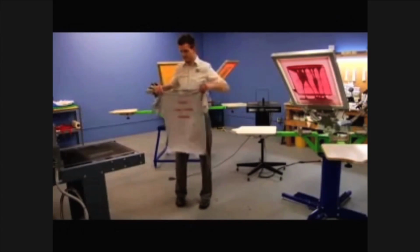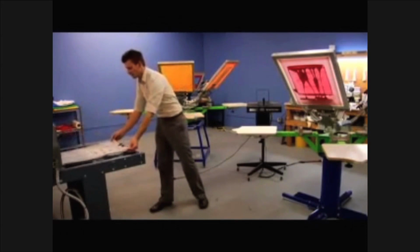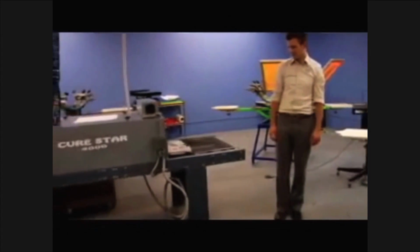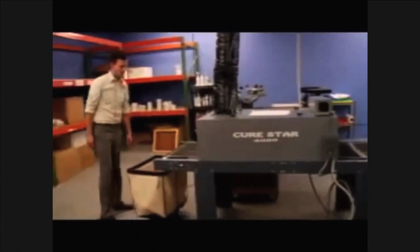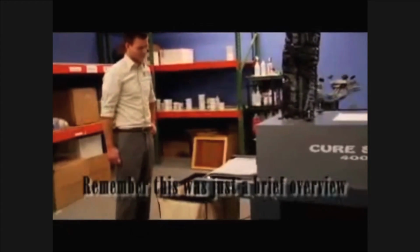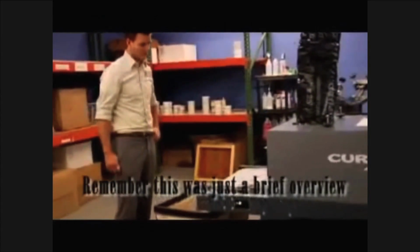When you're finished printing onto your shirt, you need to do a final cure of the shirt so the ink is completely dry for long-term use. Again, you can use a flash dryer or conveyor dryer for much quicker, more efficient drying. Once a final cure is done correctly, the shirt is ready for wearing and will last a very long time.